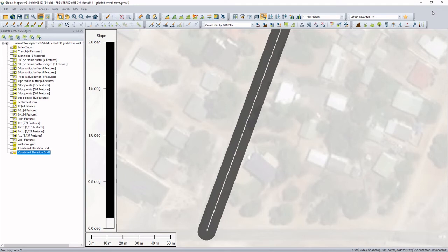I can't do this really from a grid directly, even one that's shown as a slope, because it effectively works a bit like a raster. So in order to generate something which I can query against another vector layer, I need to vectorize this 1 in 500 plot.